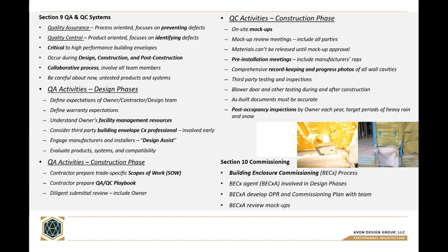So if there are any issues in the future, when you get to blower door testing, you can start to get a picture of where issues might be, rather than having to tear down entire sections of the envelope. You can start in a progressive fashion to figure out where the issues might be.